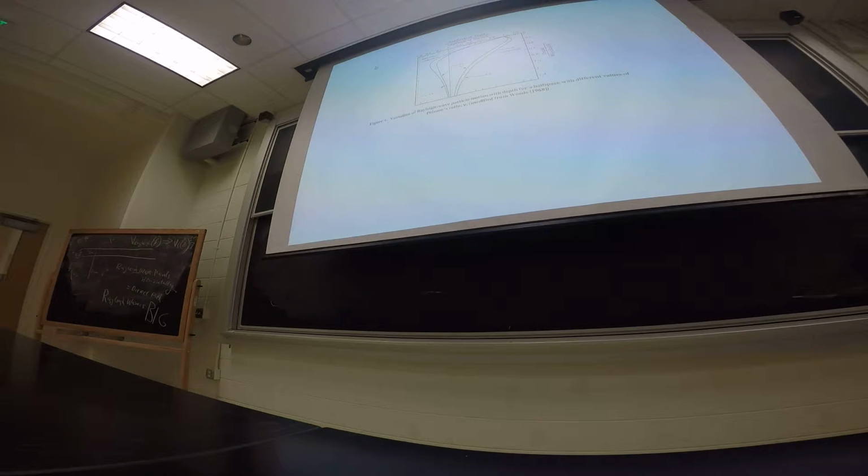So this picture basically is a composite, again, of what I just showed you. On the horizontal axis is the amplitude of the Rayleigh wave at depth divided by the amplitude of the Rayleigh wave at the surface. So you can see that at the surface, the amplitudes are the same, and so you get a fraction that's 1. And then we have two different components of the Rayleigh wave, because the Rayleigh wave has motion in two directions. It's got a vertical motion and it's got a horizontal motion.